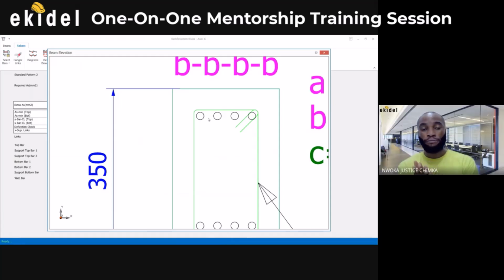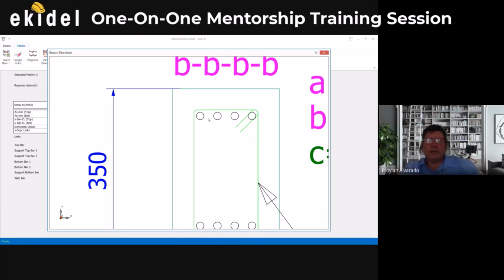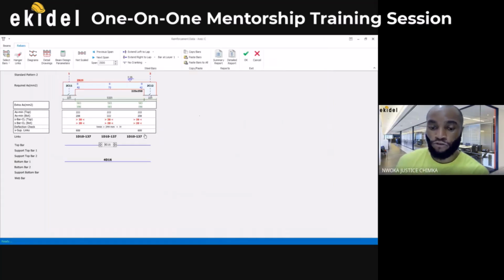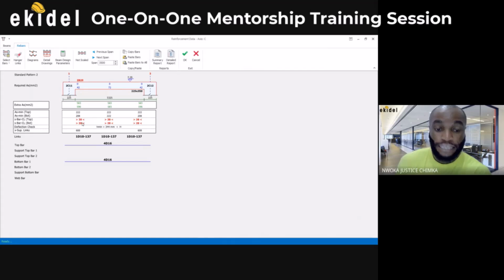That concrete stone cannot pass through this spacing of reinforcement, except you use machine vibrators. Exactly, to vibrate it. But just to avoid that, because most times you might not be at site when that will happen, make sure that your spacing between reinforcement, this spacing here, is at least 20 and above, so that concrete can pass through freely, without any issue.